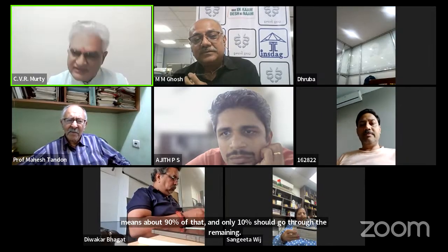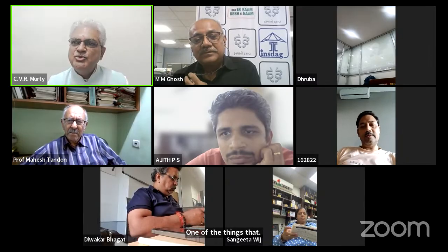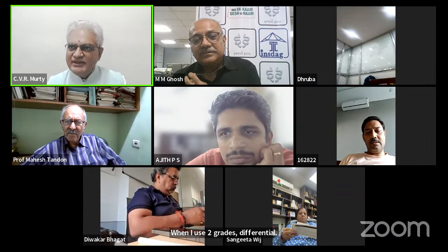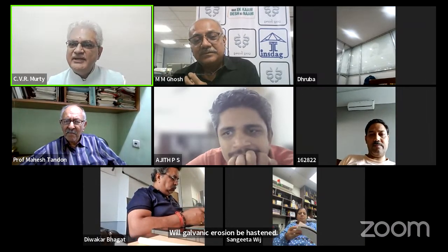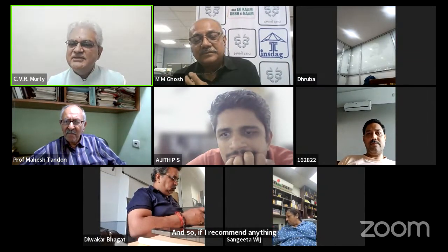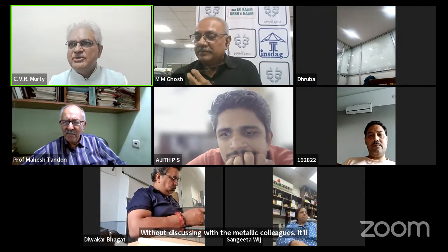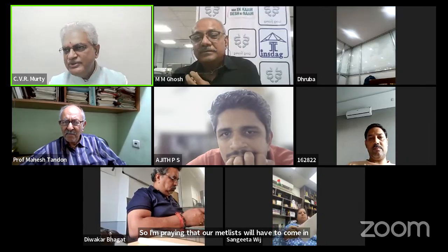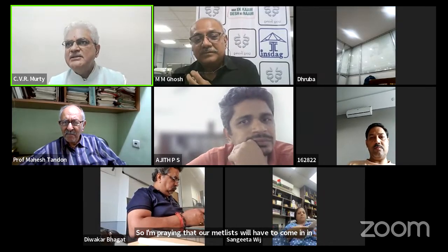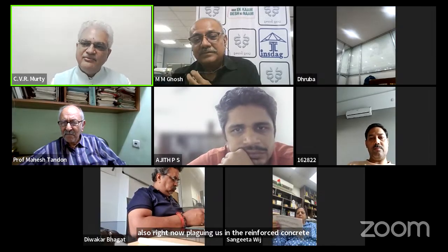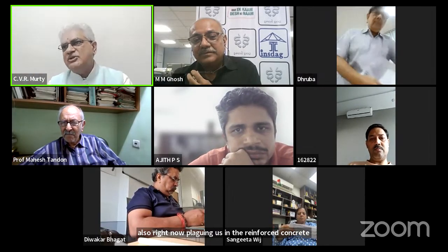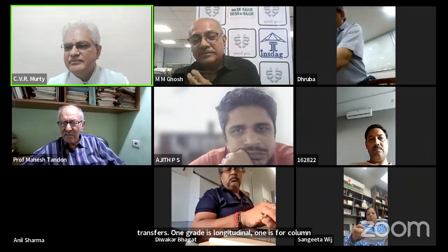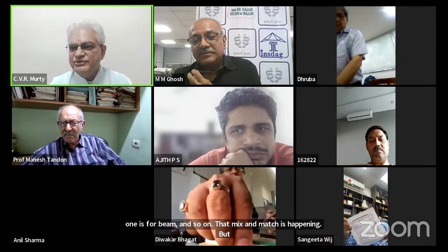One of the things that is yet to be examined seriously is, when I use two grades, differential grades, will galvanic corrosion be hastened? That is where the worry is for us. And so if I recommend anything without discussing with the metallurgy colleagues, it will be improper. So I'm praying that our metallurgists will have to come in a big way to answer this very important question. This is also right now plaguing us in the reinforced concrete section, where we are using one grade for transverse, one grade for longitudinal, one for column, one for beam, and so on. That mix and match is happening, but IS 456 will resolve that matter soon for you.